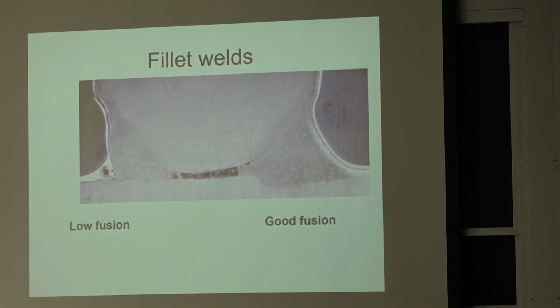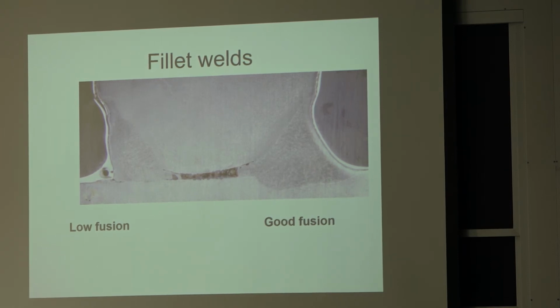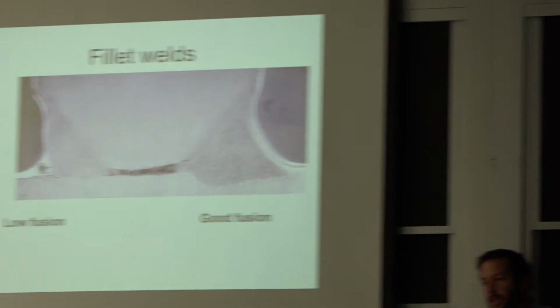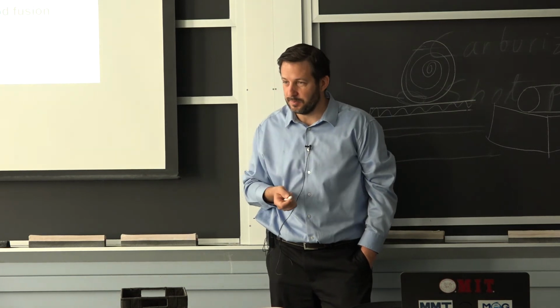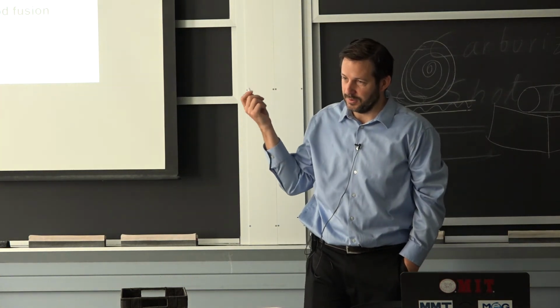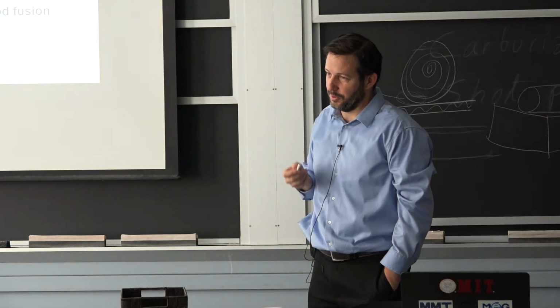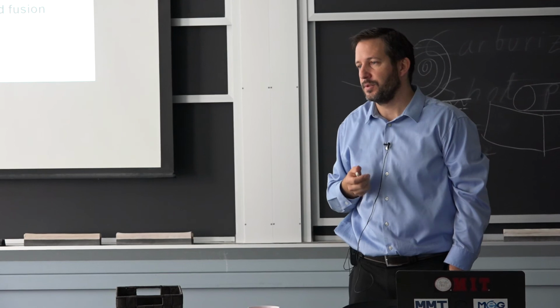So it may look like an unusual case, but what happens in this project is they didn't do a good job in the first place. Now, it was done overseas, which is just part of the reason. The main reason, it's a difficult geometry, because when the customer asked them to redo the work, you could tell that they took very, very special care, and they still had issues like this. So this was a quality assurance verification on the replacement one, the better one. The other one really had almost 25–30% of the joints that were not fused.